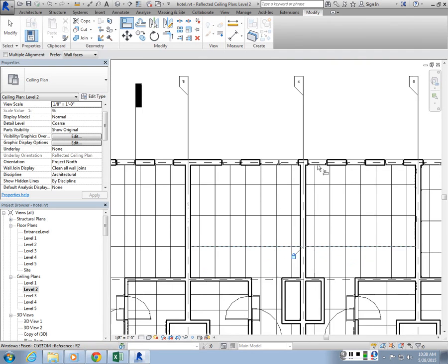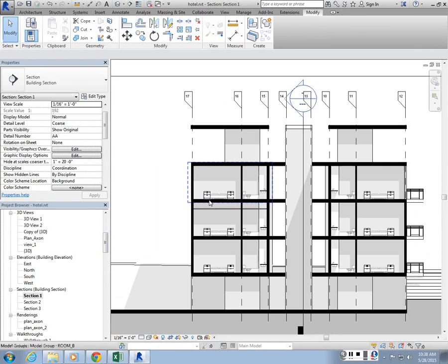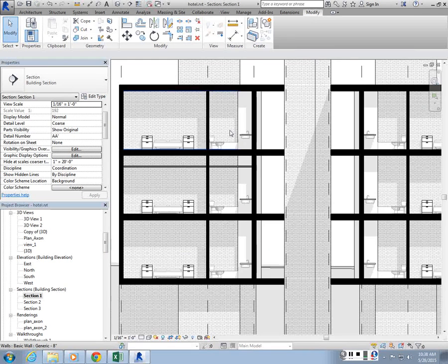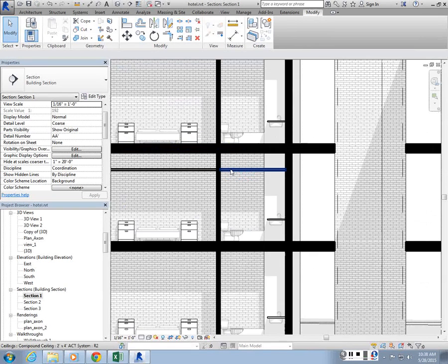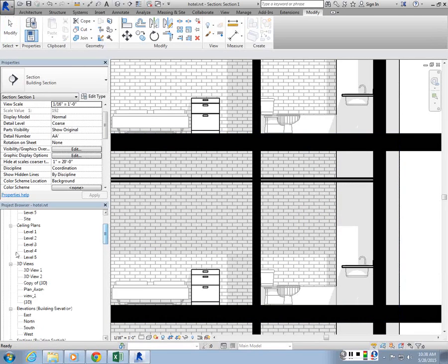No, you first put the drywalls, then put the suspended ceiling. Right? So if you look at the section, let's look at the section. So that's my suspended ceiling. It goes from wall to wall. Yes. So that's why you would need these walls to support it, right? Because that's how that's going to be attached. Otherwise, if it's suspended, you will have frames coming down from the ceiling to hold it.